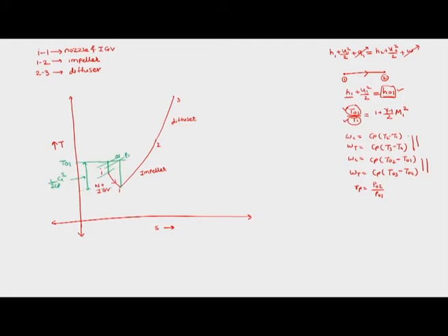So this is P01 and then this is P2. Now we will stop the flow at 2 to go to the stagnation state. As we have seen, we are considering an imaginary process, which is an isentropic process, stopping the flow to go to the stagnation conditions.